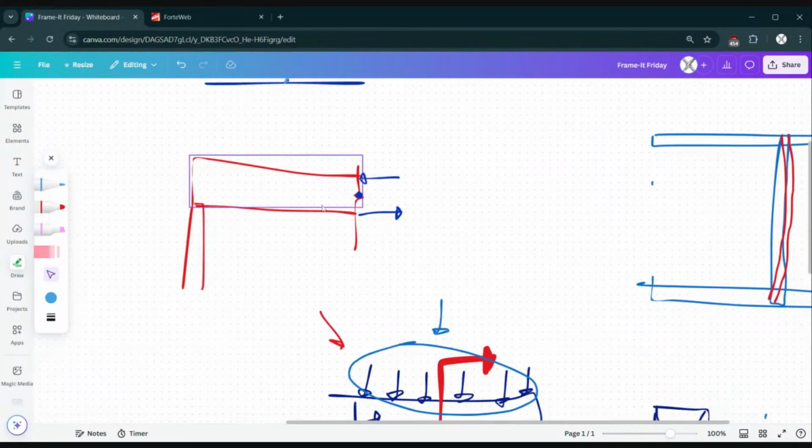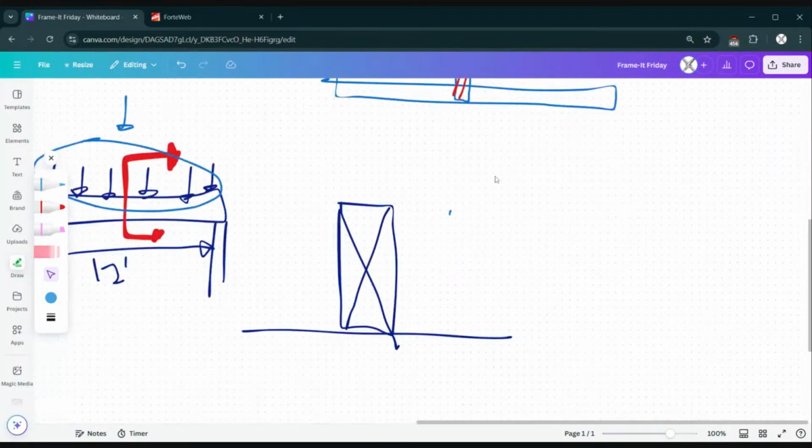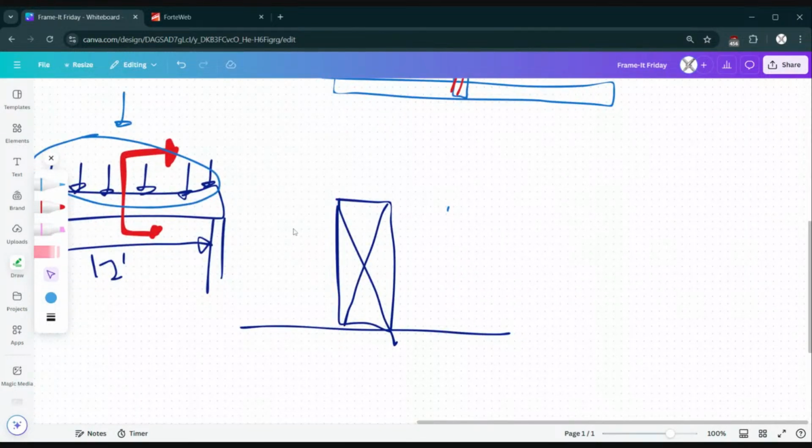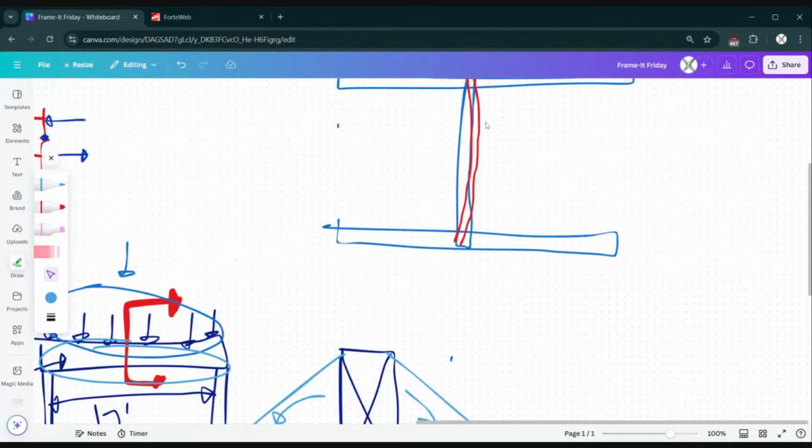Okay. So the same thing happens with the top of the beam because it's being squished. The top of the beam bows out like this. Therefore, if we block the whole beam with these side angular things or some other way and restrain it from rotating left or right down the whole length of the beam, then we actually can make the beam stronger.